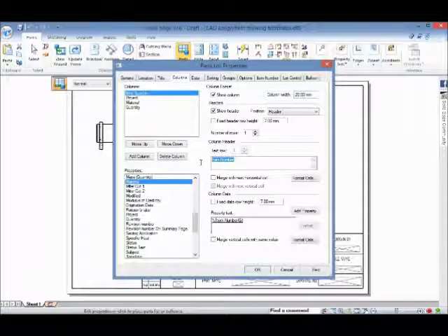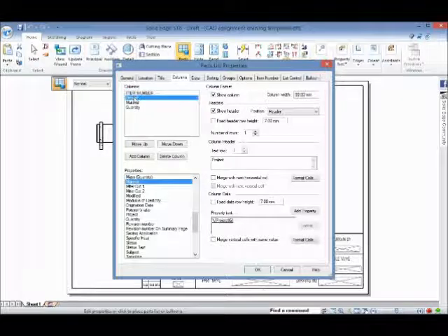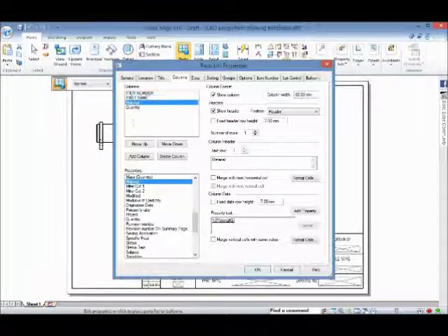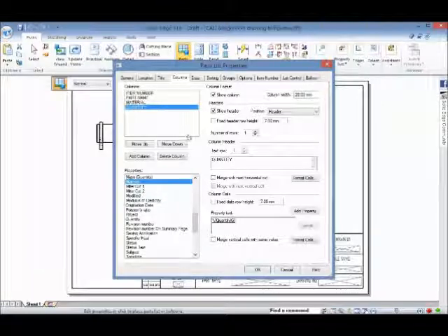The next step is to retype this column name in capital, because all the names appearing in the title block must be in capital, which is recommended by British Standard. So you can highlight one and type the capital here and do one by one until they are all finished. So now we have four columns. One is item number, the other ones are names, materials, and the quantities is the last one.